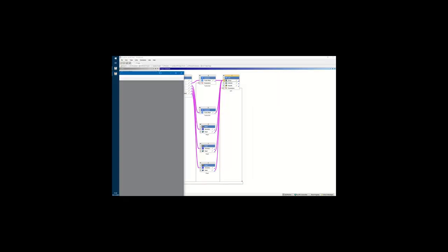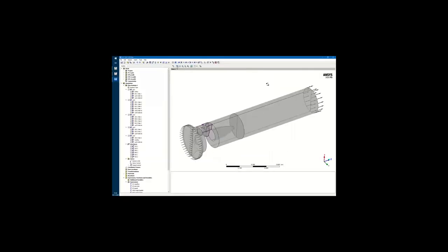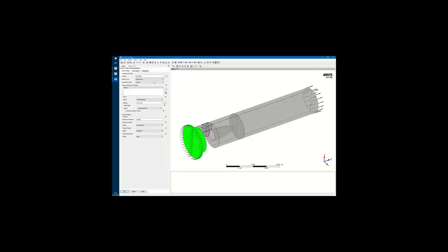And let's take a closer look at the setup in CFX by opening CFX. And as I mentioned, named selections are created automatically for your turbomachinery components. And you can use them inside of Ansys Meshing, CFX as well as CFD Post to apply your settings in a comfortable and more robust way. And so, for example, in CFX I have used them to set up my fluid domains.